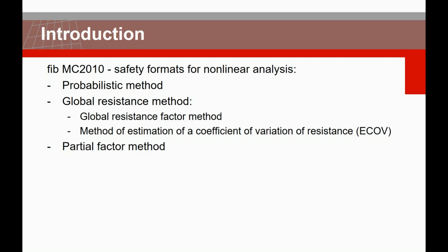In that method, you do a variation of all the input parameters, as well as a variation over your structure element. By those variations, you should be able to figure out the reliability of your structure and of your analysis as well. So which safety factors should I use?